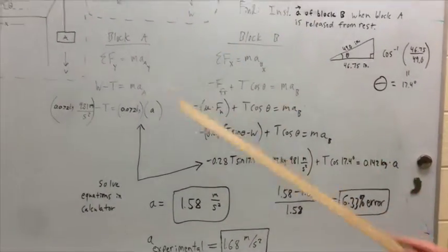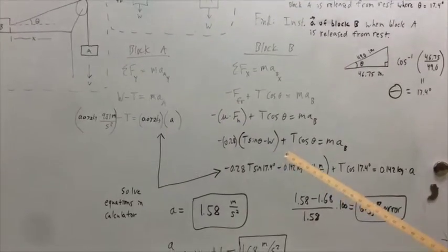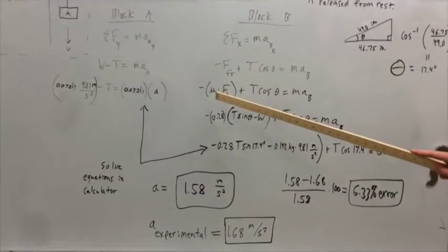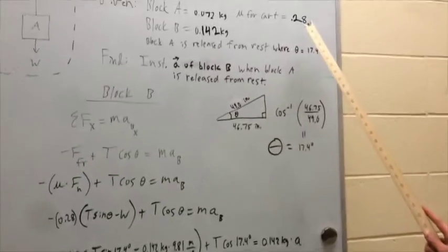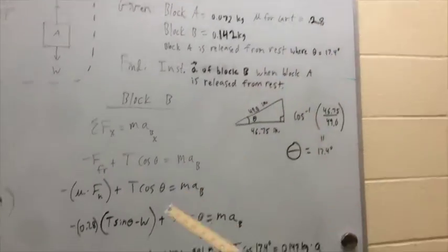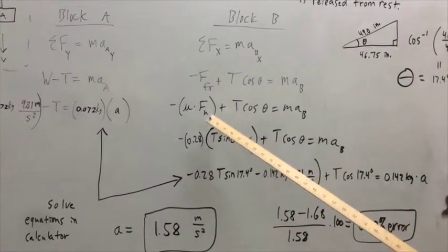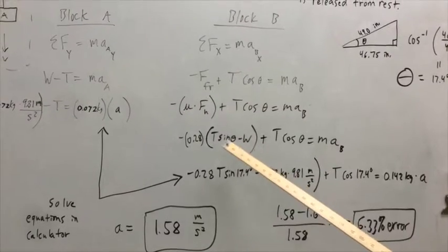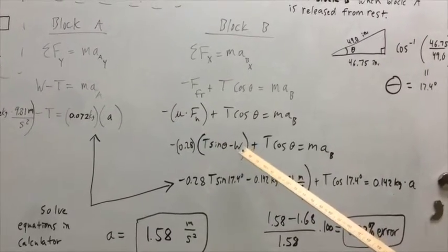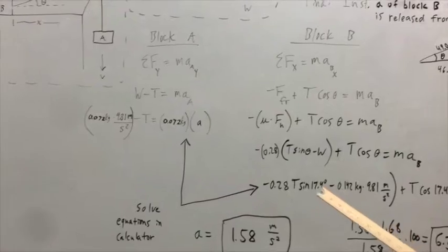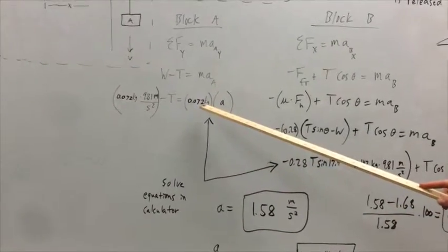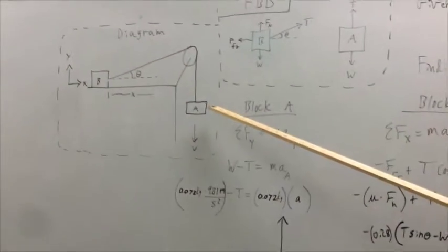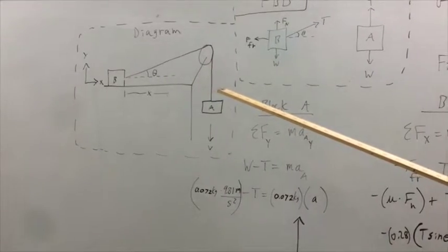So we did the same basic calculations as previously, but accounting for friction, so we have a value for mu of 0.28 for the paper on the paper. And the normal force is related to the y component of the tension and the weight. So following the same calculations as previously and changing the value of the mass A to overcome that new friction